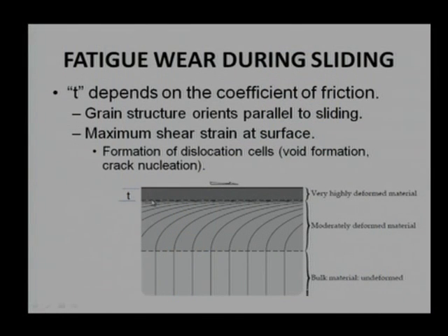That is the reason why, when T is smaller, in a bimetallic material where the top layer has a very small thickness, there is more bonding and a lesser number of voids will be generated. But if the thickness is on a higher side, then the bonding will be slightly lesser, more voids will be generated, and delamination of that layer will be much easier. That is why I say that we need to design the thickness properly, for a surface undergoing a very high shear rate.